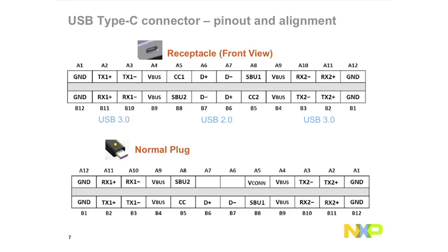You have the appropriate VBUS and ground pins for power and ground. And then you see some sideband signal pins called SBU1, SBU2, as SBU stands for sideband signaling. And also 2 pins called CC1 and CC2. And CC stands for configuration channel. So those are essentially the pins used for communicating any configuration messages between 2 sides when they are connected over Type-C. So you can see how there is a provision to send all kinds of signals through this pinout.